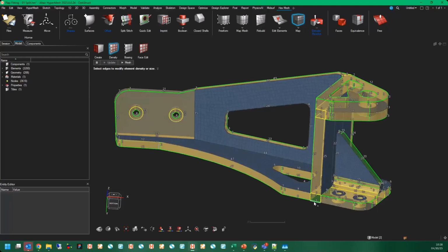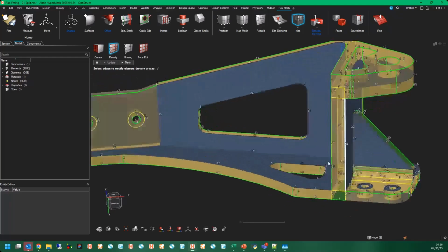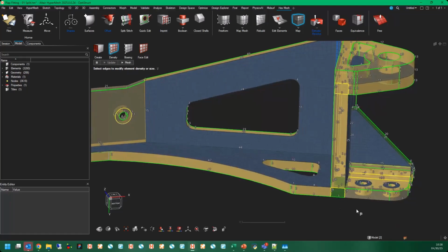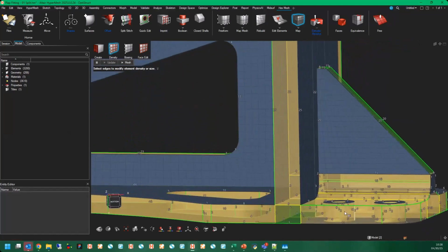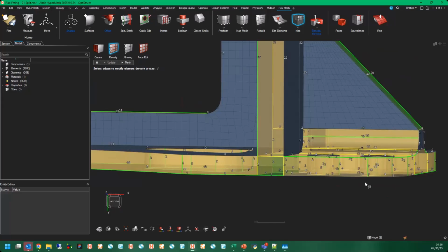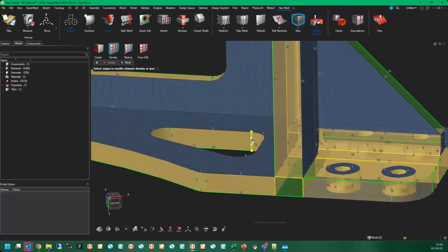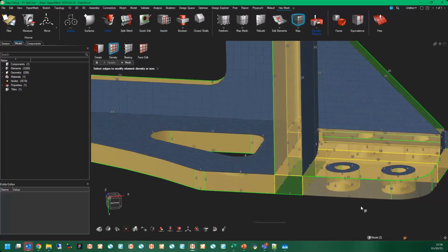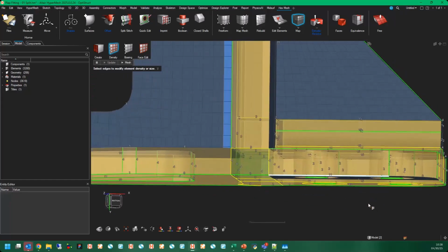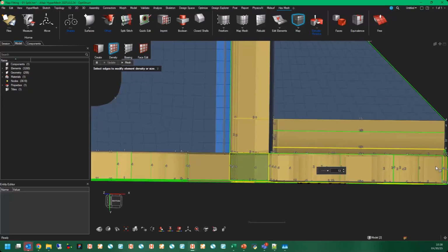All right, and just that quickly, it goes through and identifies all of the source surfaces, seedings. It also puts seedings on the through the thickness directions that you can update. Like in this case, say I wanted 4 elements through the thickness everywhere. I can update that, and as I update that, it changes most everywhere. On holes, you have to go do them individually. You can also, like for these 4 holes, do a window selection and then just say, I want those all to be 4.